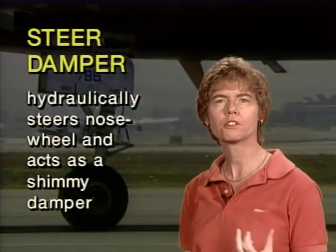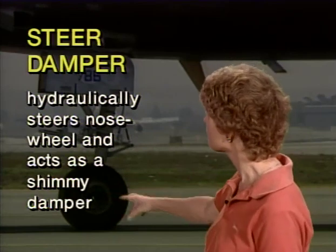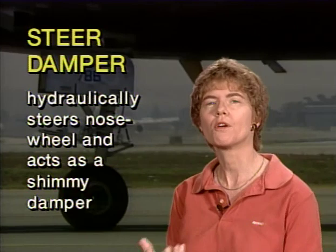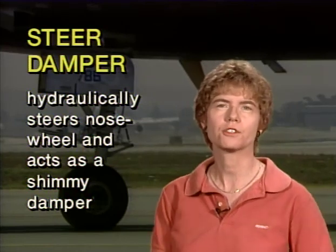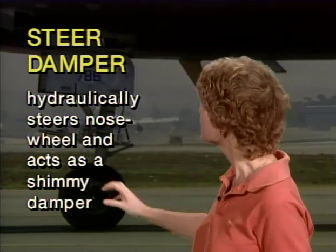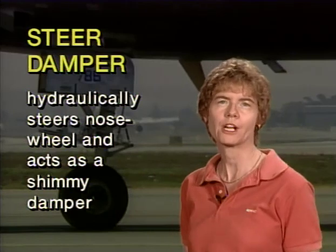And the purpose of the steer damper is twofold. First of all, it hydraulically steers the nose wheel. This is on aircraft like 727s and the large airline aircraft where you have hydraulic steering instead of just using the rudder pedals. And the second purpose of that steer damper is that it acts as a shimmy damper to keep that nose wheel from shimmying.